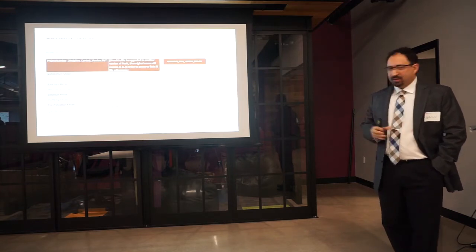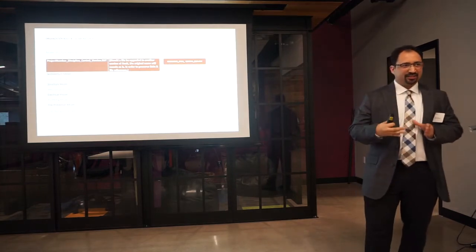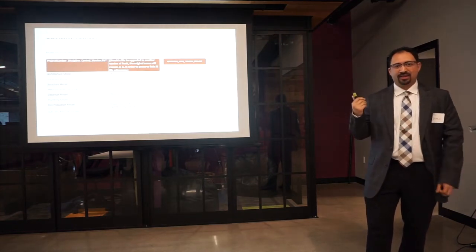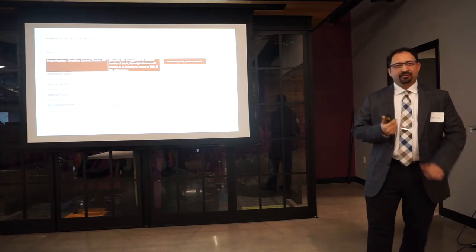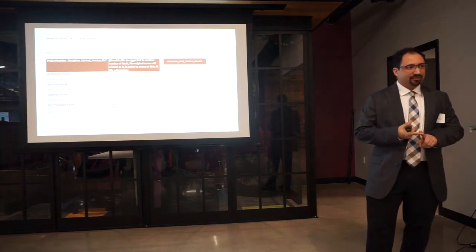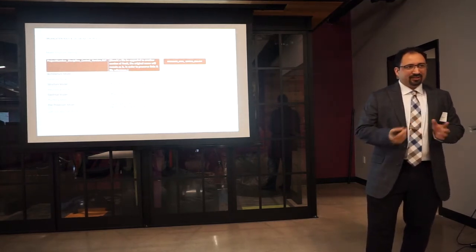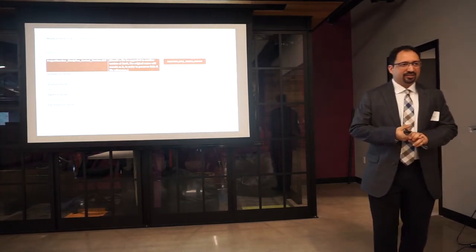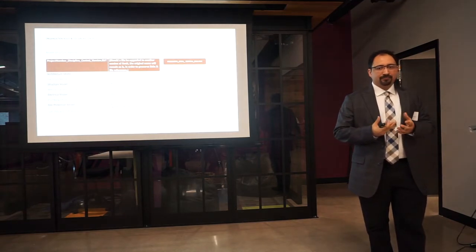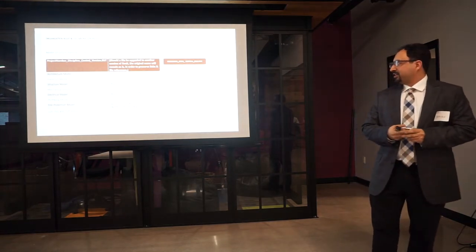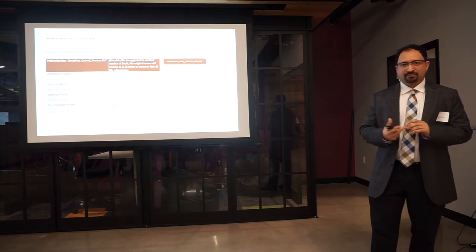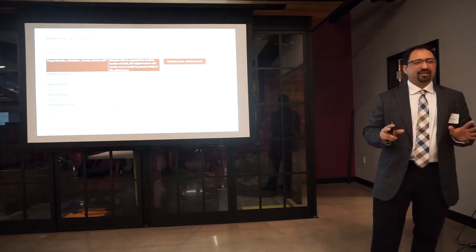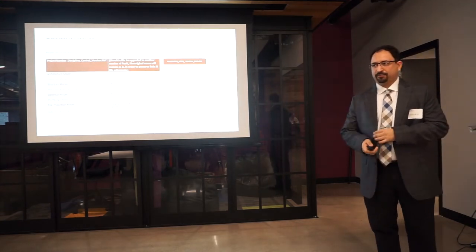So we set up the instructions. Like I said, this is a big instruction manual, so we set up the file structure. Every single group had to follow this strictly. If we didn't follow this strictly, it would cause problems with the linking of the project. With Revit, just like AutoCAD, if you don't have the right name, it won't find the file. It can cause issues with our prints. So we were very strict about it. Even when the project would upgrade to another version of Revit, we kept the same naming convention just to prevent any issues with the drawings.